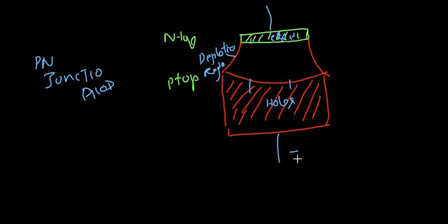The n-type is connected to positive and the p-type is connected to negative. What happens? It will be attracting in this direction, and the carriers will be moving away. Thereby, the depletion region will be increasing. Because of this increasing depletion region, there will be no current or very little current. This particular arrangement is called the reverse bias condition.